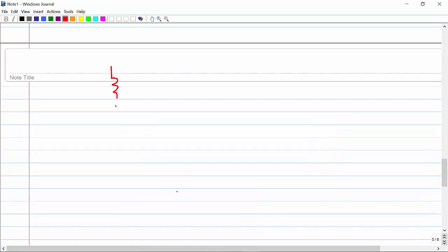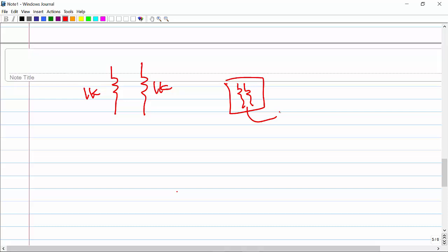So if you make two resistors of 1K and 1K in an IC, and you place them very closely, and if you measure, there will be a small difference in the value, and that is called the mismatch. This is very important because suppose you have a current mirror.